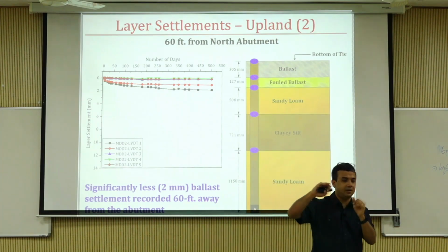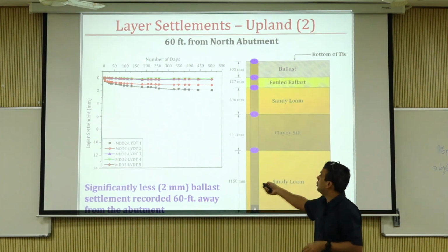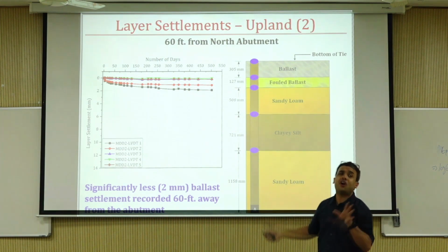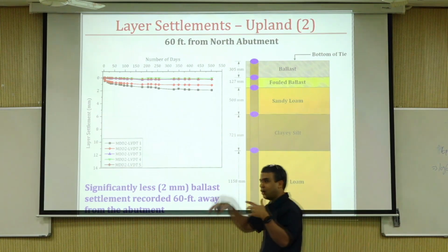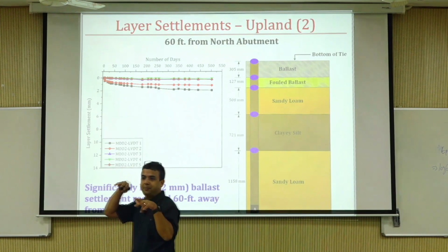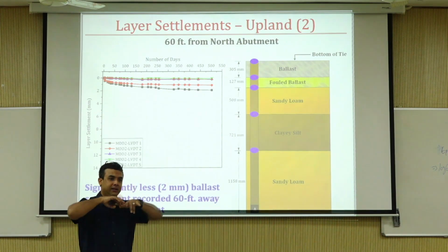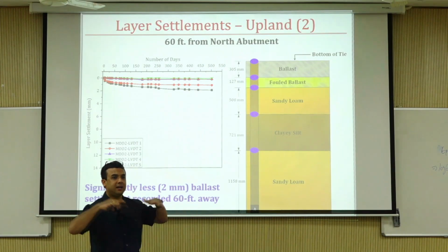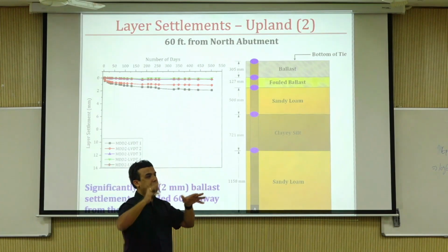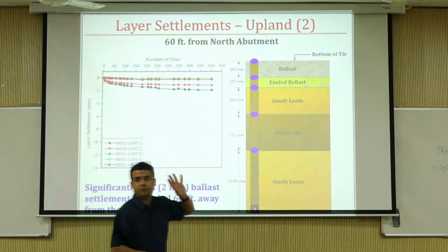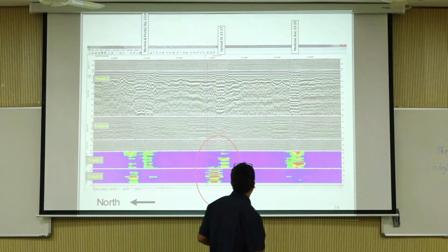They're stabilizing, however the material is. So look how less the permanent deformation is. It's not just stabilization, by the way. There is a lot of stress wave reflection happening, because when the trains are moving, the stress waves move through the layers, right? They actually rebound from the abutment and they cause all sorts of havoc. That's basically that.